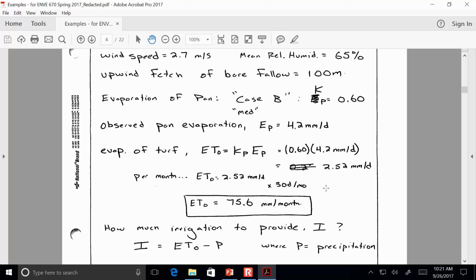And this is the first time that we've thought about a water balance. We're going to do this a lot more, especially when we start talking about runoff, the idea of water balance. If you think about it, the water has to go somewhere. It's either going to infiltrate down into the soil, or it's going to be incorporated into the mass of the plant, or it's going to evapotranspirate into the atmosphere. So this is the simplest conception of a model.